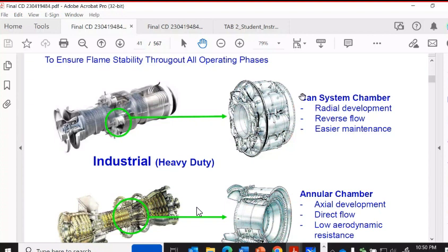And so I may try to compensate through other chambers, and that can cause some premature damage to my high pressure turbine nozzles and blades themselves, and it can cause premature damage in the combustor cans. So like I said, this was the beauty about this from a mechanical standpoint. It's really easy to come into a can system, open up the casing, take one of these combustor cans out, replace it with another one, close the casing back up, and you're back in operation.